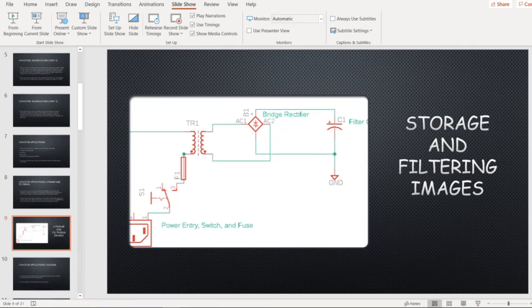It is a fire waiting to happen, or an electric shock hazard, depending on which configuration they have. I won't go into which one is for what, because it's really not that important. Just know that those are bad capacitors, and generally speaking, they're used for filtering. The reason why they are is because they fail open.